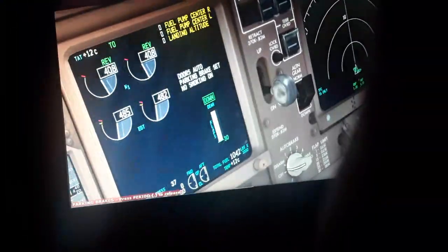This is the takeoff ground. You press it and it arms takeoff. So you need to press again the other throttle disengage, and it will disarm like this. Speed brakes again. This is also another function of the thrust reverse. If you move up this handle, it will reverse the thrust.